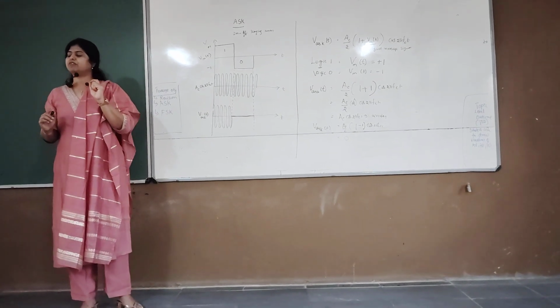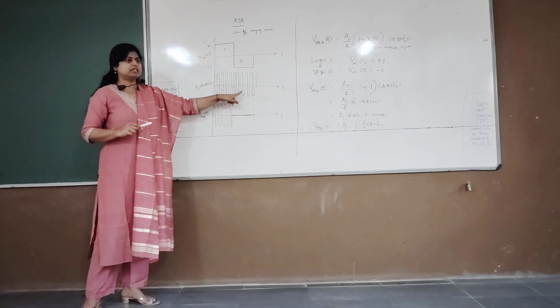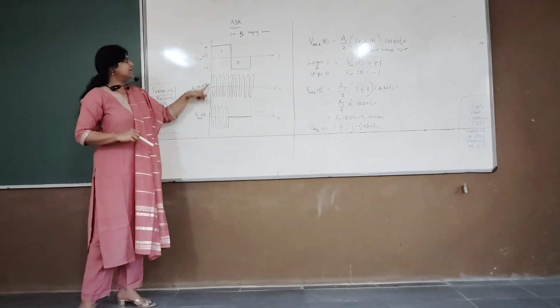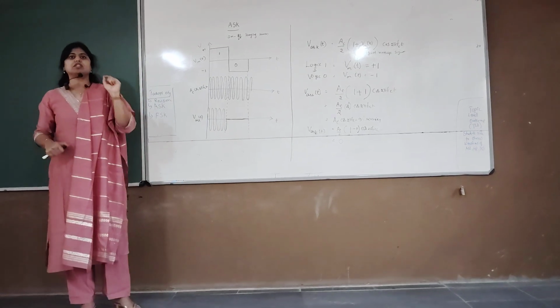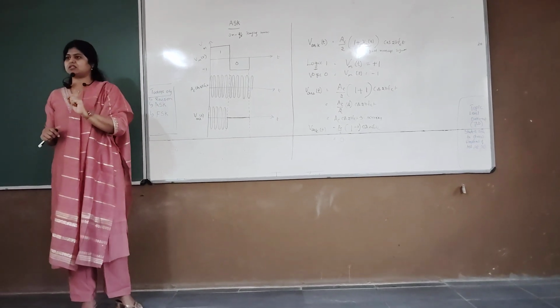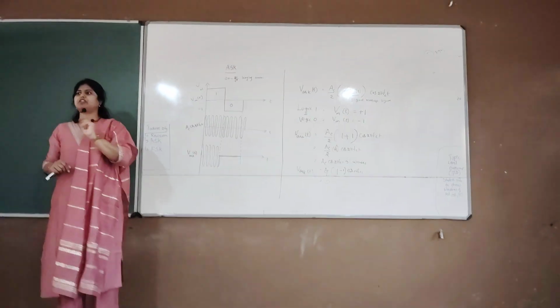Till now we worked on only amplitude. Your frequency is kept constant. You can see there is no frequency change here. Even the phase of the signal is kept constant. Only we worked on amplitude, and that is the reason we call it amplitude shift key.